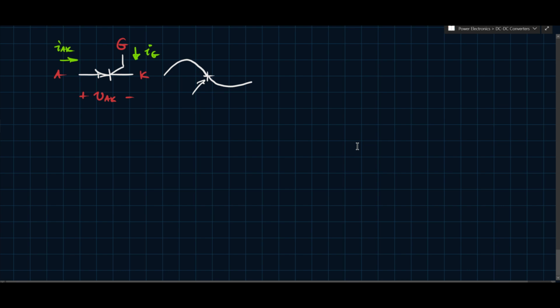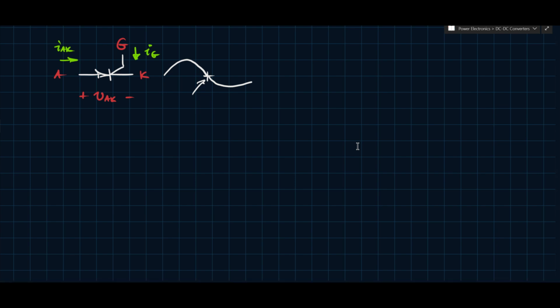What we're going to do in this video is look at these silicon controlled rectifiers, or thyristors, and how they're used in what we call phase controlled converters. We're going to focus mainly on rectifiers in this type of application. Although the rectifier and the inverter, depending on the way you modulate them, can use the same topology for both, as we've seen in the cases of AC to DC or DC to AC converters. We've mentioned before that all you really need to do is change how you control the switches, and you end up with a completely different converter.